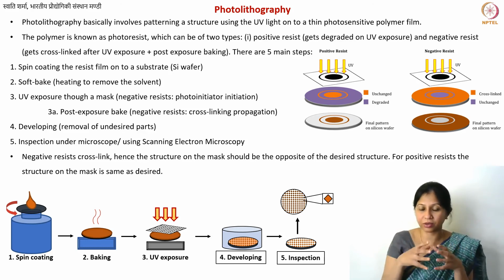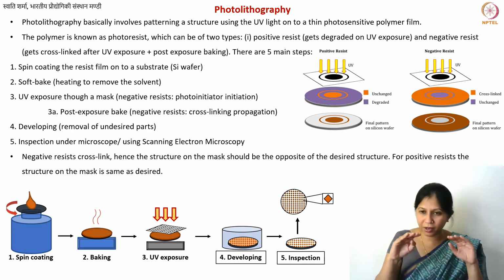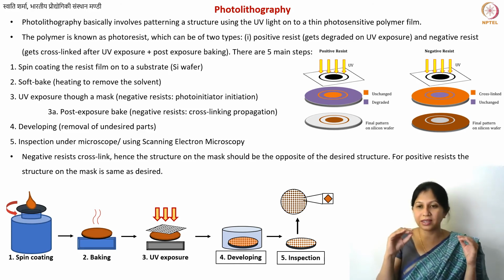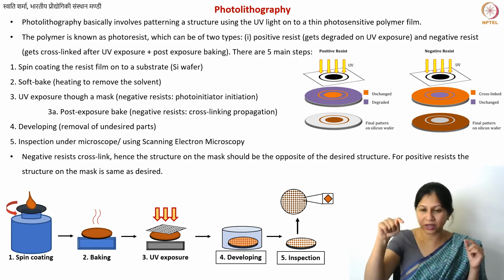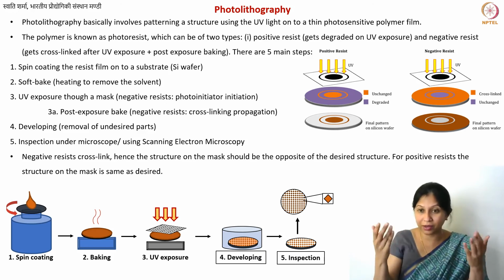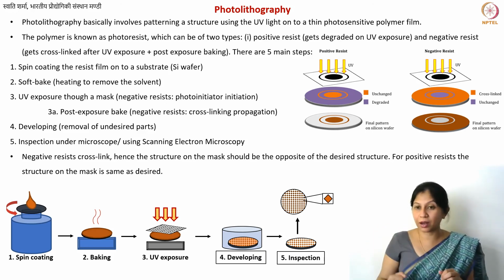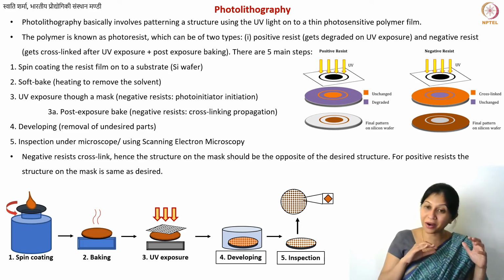what is known as an oxidation furnace. So you have oxygen there and high temperature, and the top layer of silicon itself converts into silicon oxide. The interesting part is that this oxide layer is electrically insulating. And sometimes you can create certain windows in this layer by using lithographic techniques, for example, and then etch the oxide through that window. So you can selectively get parts of your wafer which are electrically conductive and parts that are not.